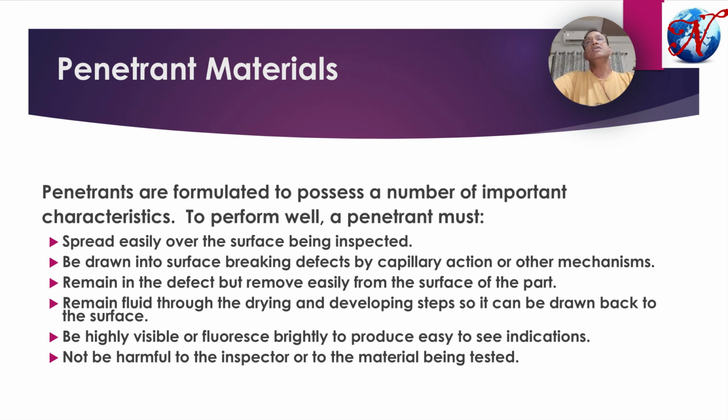It shall have a nature such that it will be drawn into the surface breaking defect by capillary action or other mechanisms. It will remain in liquid form during the penetration dwell time. It has the ability to dissolve the dye such that we can produce the specific color of the dye, like a visible dye, red in color, and a fluorescent dye, which is green to yellow in color.